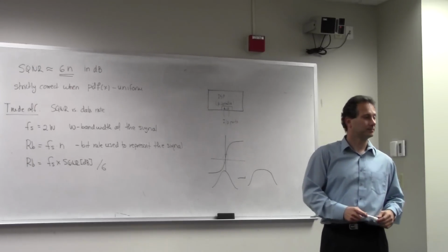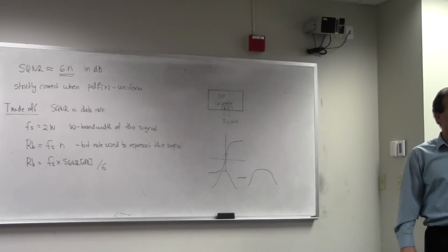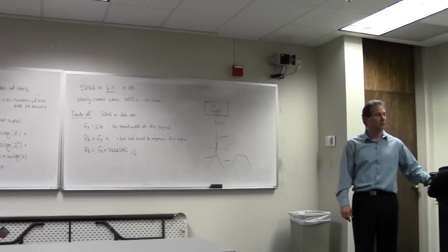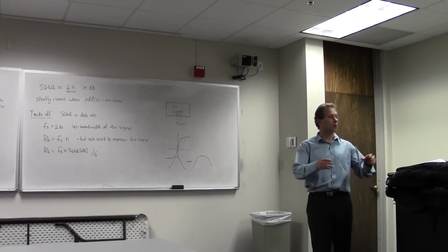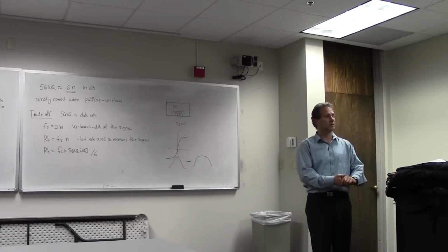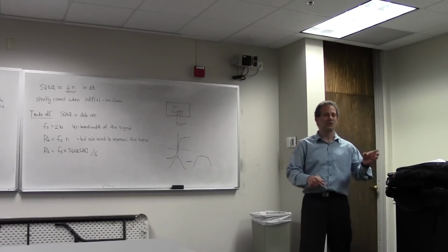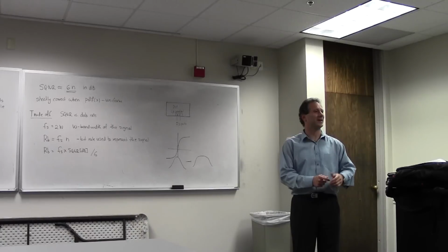Last question. Actually, in a theoretical way, what is the purpose of the compression? It transforms the PDF of your signal from non-uniform to uniform, or close to uniform. So therefore, it's more suitable for uniform quantization. In a particular way, it makes your signal become tight, something like that in the behavior of the signal. You're now using musician's terms. Yeah. Compression makes your signal tight, right? That's how a guitar player would say.